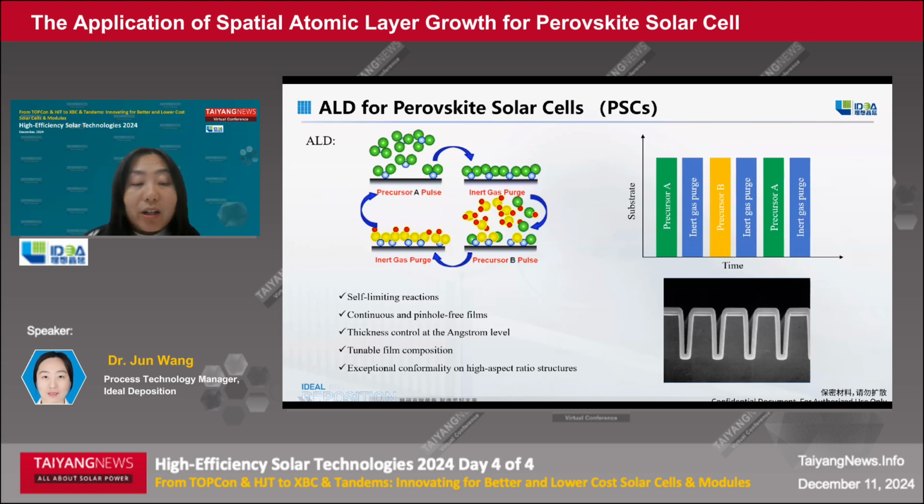These surface reactions are self-limiting, yielding one monolayer per cycle, and the purging step prevents the mixing of the precursors, which would otherwise decrease the uniformity of the deposition. The deposition cycle is repeated until the required number of deposition layers is achieved.